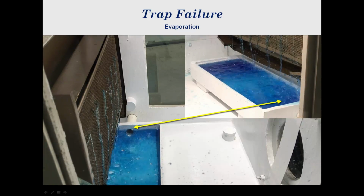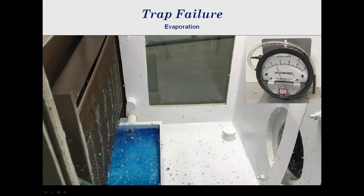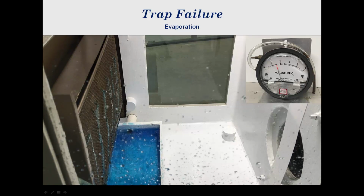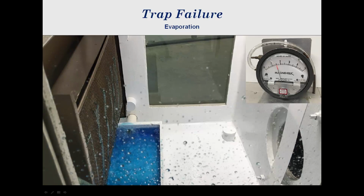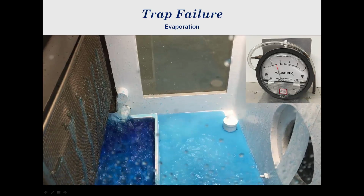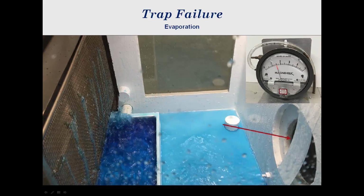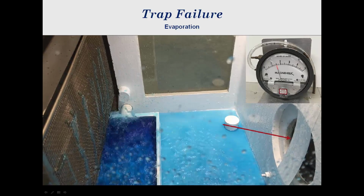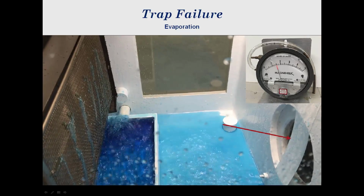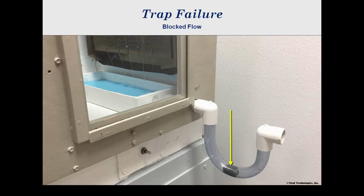The two views show the blowing of condensate as the drain pan fills. Now, at 1.5 inches of water, condensate blowing becomes intense. Flow cannot occur at this pressure because water will overflow from the drain pan before drainage can begin. Also, as shown by paper placed in the blower airstream, water particles can be carried into the ductwork and cause damage to insulation and other components.